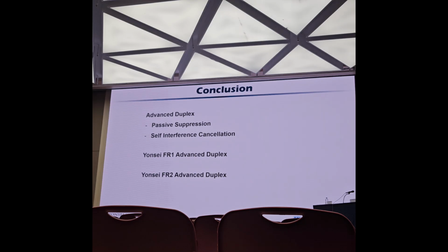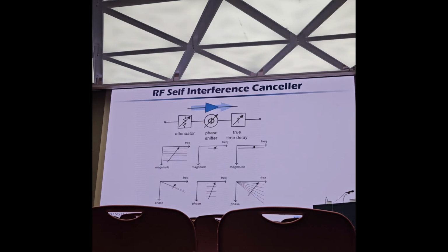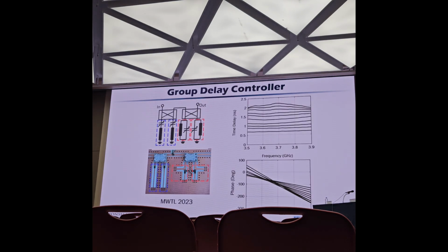If not, I think the initial work, what you had shown around the 3 GHz band, your group delay, or the group delay of the linear phase, is very narrow band, within 200 MHz, right? Why is it so, or is your specification like that?